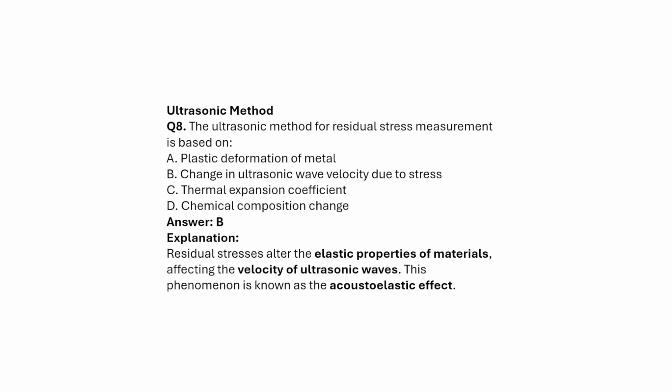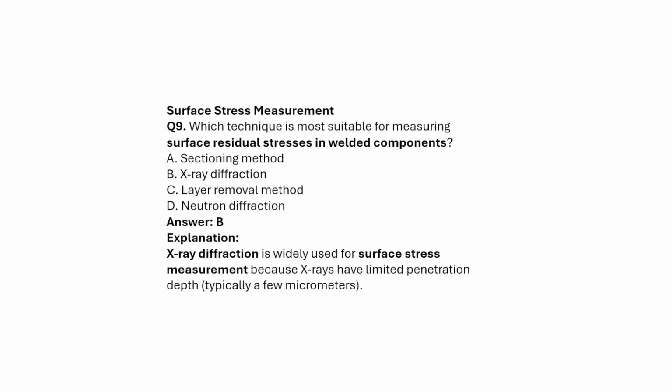Answer will be B. Change in the ultrasonic wave velocity due to the stresses. Okay. Residual stresses alter the elastic properties of the material, which affects the velocity of the ultrasonic waves. This phenomenon is known as the acoustoelastic effect.